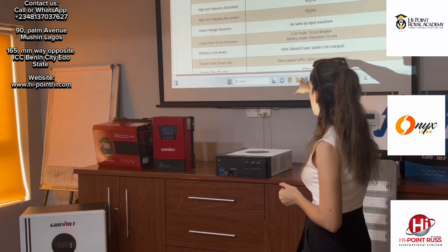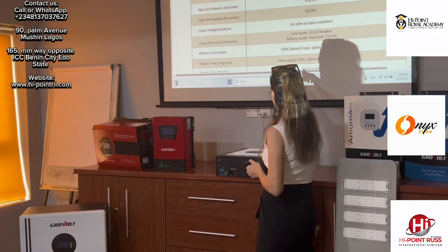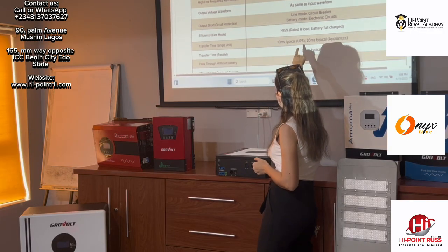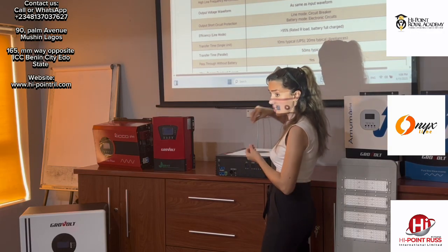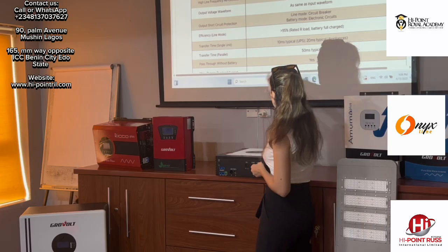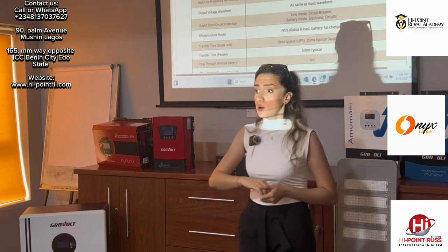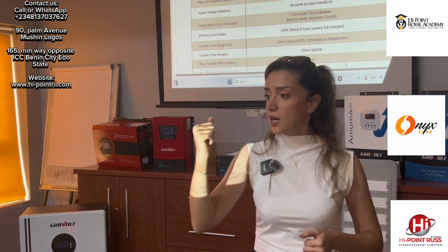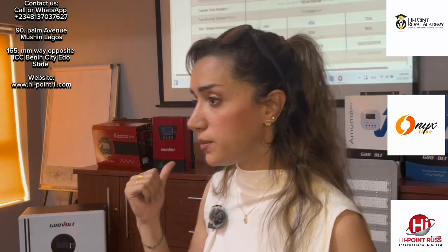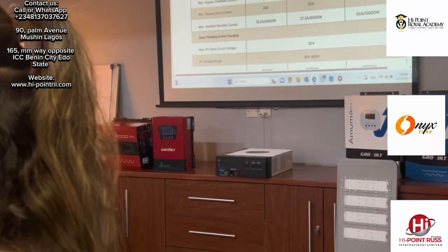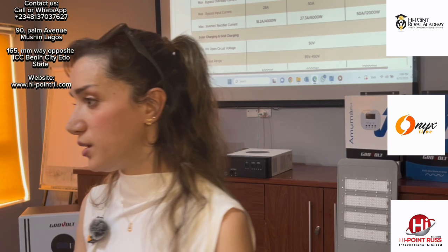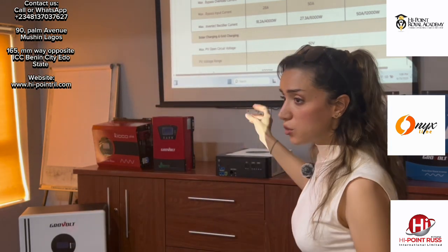Okay, the transfer time in this inverter, if you use UPS type inside the inverter by the settings, it's 10 milliseconds. But also this 10 milliseconds, a server does not accept. So they always use a UPS with the inverter. This one is very important to know.